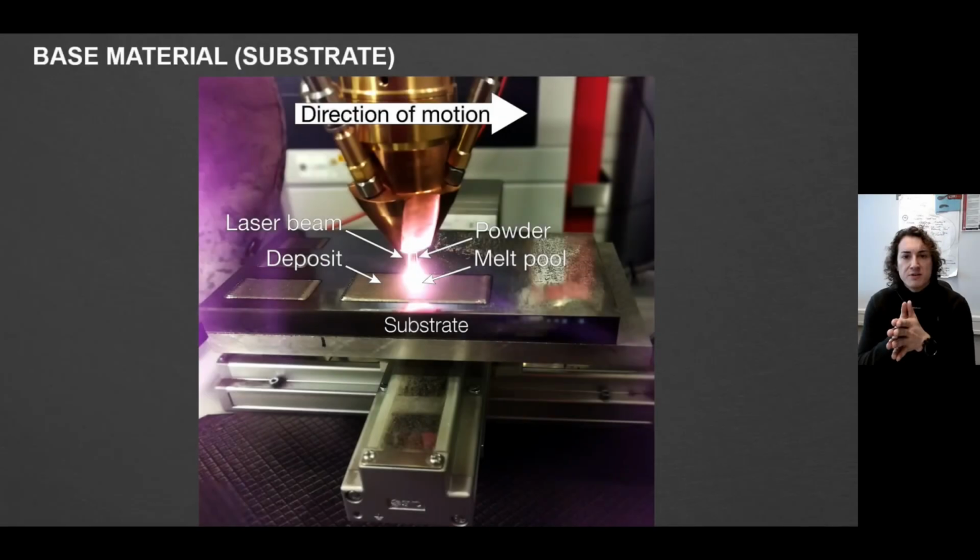My advice would be that when you, as a beginner, start to work with substrates, you always save a lot of data and you learn, and this will definitely help you in future to avoid a lot of testing and to have a more structured approach. In any hard-facing process, and primarily here we talk about laser cladding, we put our coating on a substrate. The substrate or base material usually has weaker properties in terms of corrosion, wear resistance, or any other properties compared to your coating. However, the importance of the substrate cannot be underestimated.